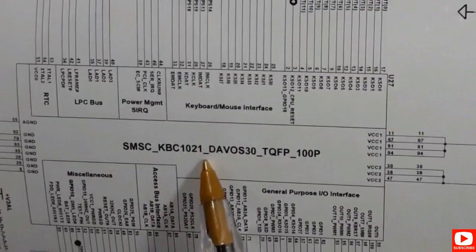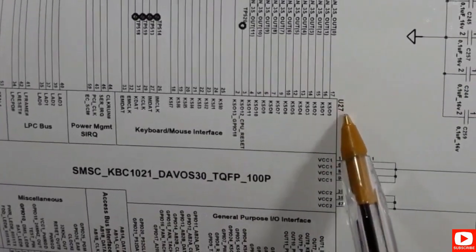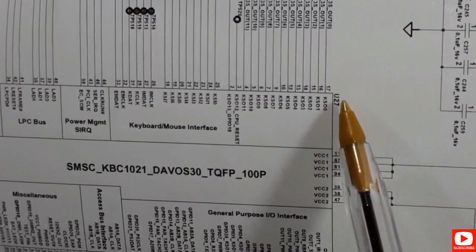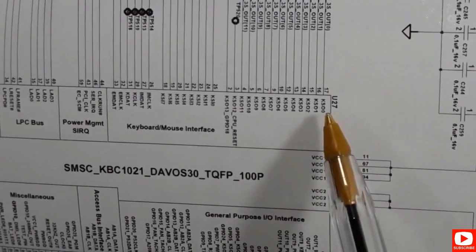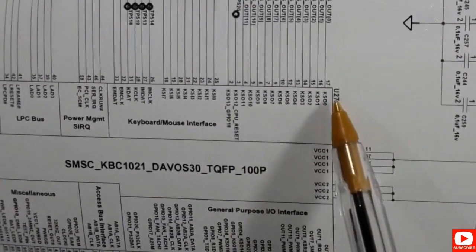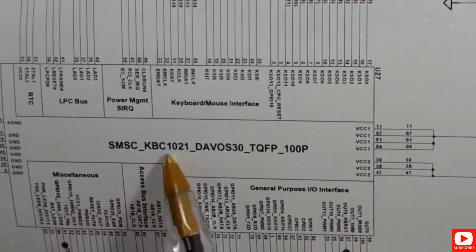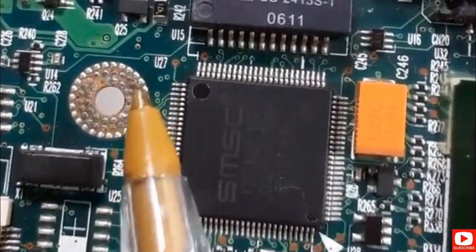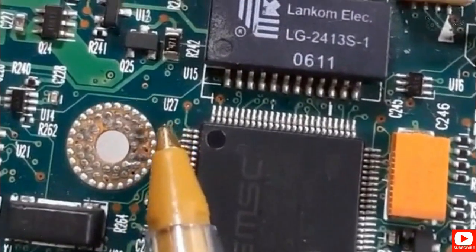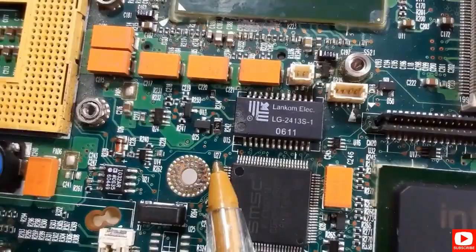Let's check the reference. As you can see here, keyboard controller 1021. We have here U27. This is the reference designator for this IC, U27. If we go to the motherboard, we should find U27 next to the keyboard controller. So let's check in the motherboard. As you can see, this is the IC, the keyboard control. Here we have U27, exactly the same as we have seen in the schematic.